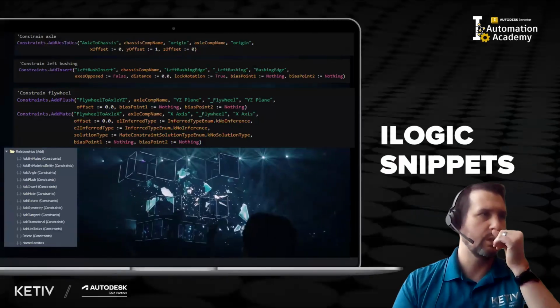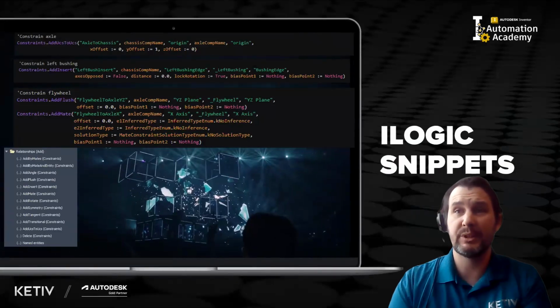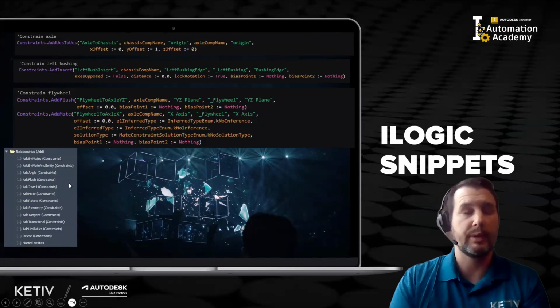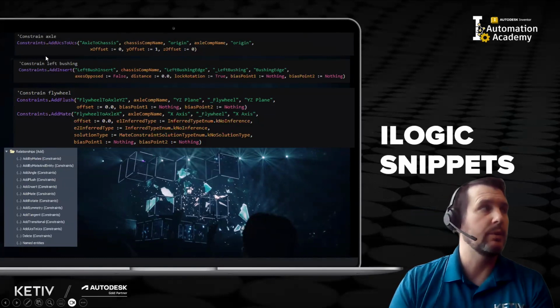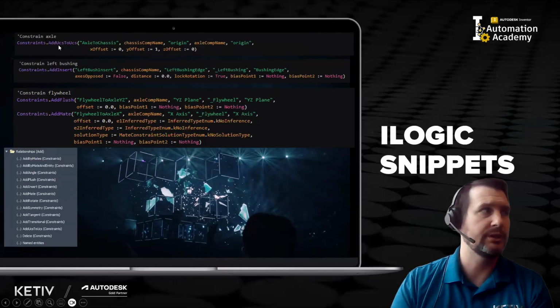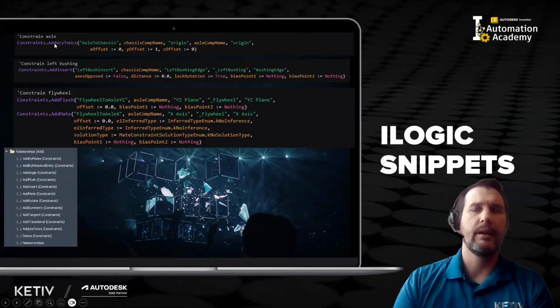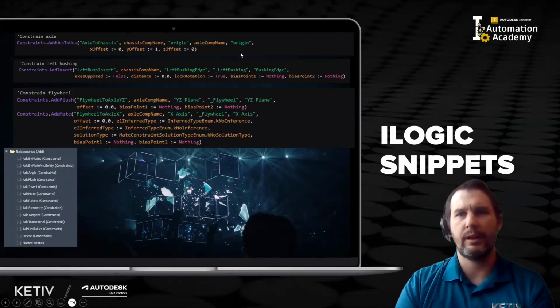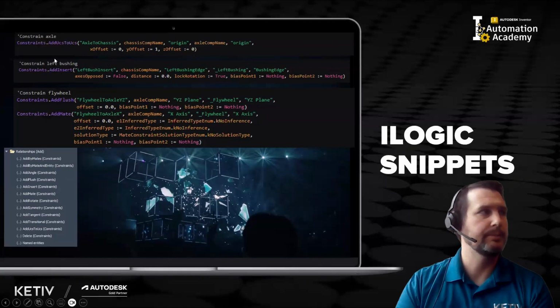Once again, we're going to be using iLogic snippets for that as well. We have this folder called relationships where we're going to get those snippets. Some of those will be add UCS to UCS. This allows you to basically do 3 flush constraints in one. So you can take a UCS or an origin and put them together.